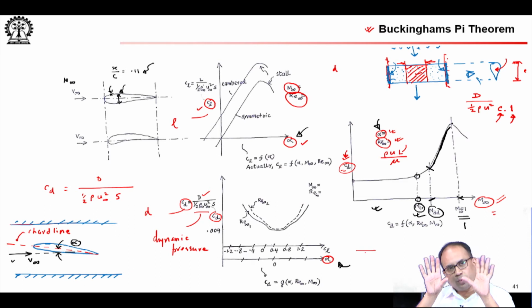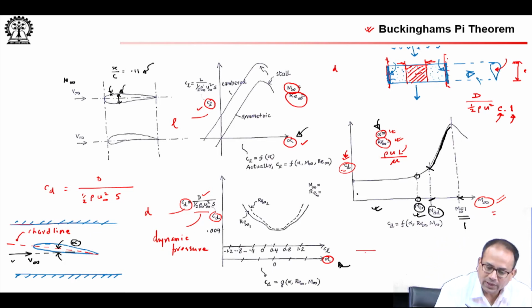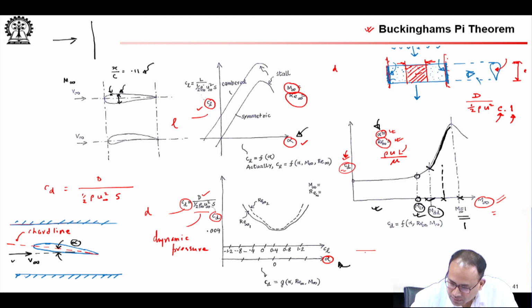we are really discussing the sweeping back of the wing. So, what happens is when you sweep the wing back, if your wing is like this and you have flow coming at a Mach number somewhere here, suppose you are flying at a free stream Mach number of this, where your section drag is somewhat like that high, it is a lot of drag on your vehicle.